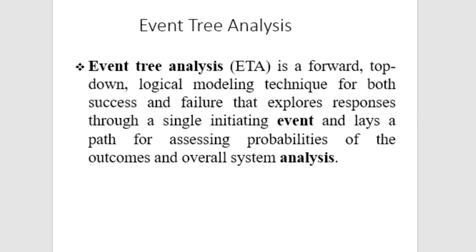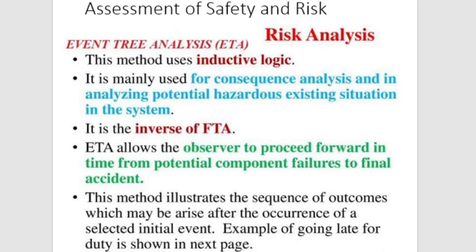Next one, event tree analysis. It is a forward top-down logical modeling technique for both success and failure that explores responses through a single initiating event. Shortly we call it ETA. Event tree analysis uses inductive logic, mainly used for consequence analysis and in analyzing potential hazardous existing situations in the system.